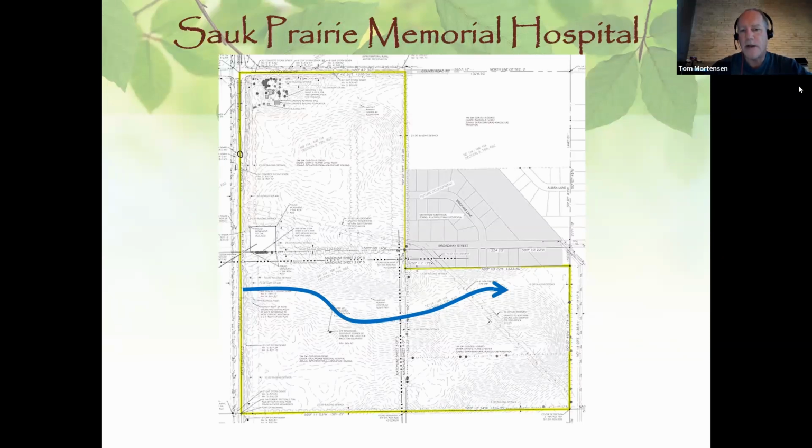And we had offsite flow from a large agricultural field across the street, and we had a state highway on the left. So this water pattern, this drainage pattern, we respected that. If we were to try to fight that and change it, it would have caused a lot of regrading and a lot of erosion. So we said, okay, let's just see what happens if we leave that intact and work around it.